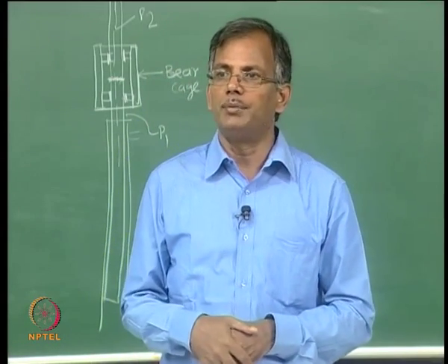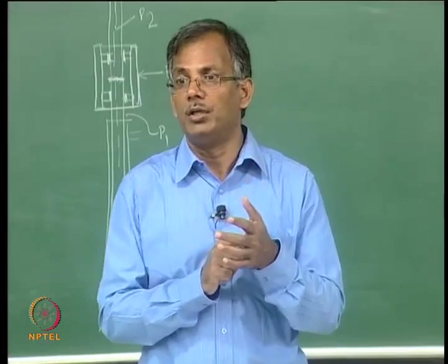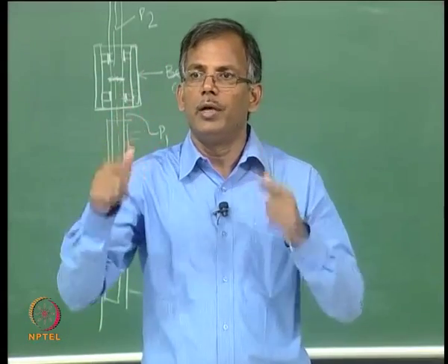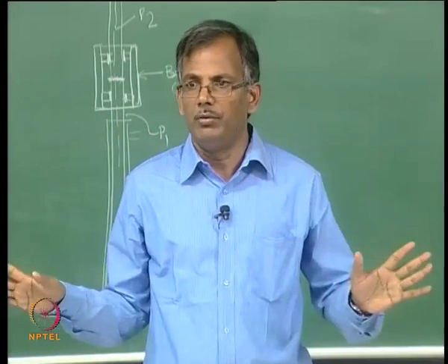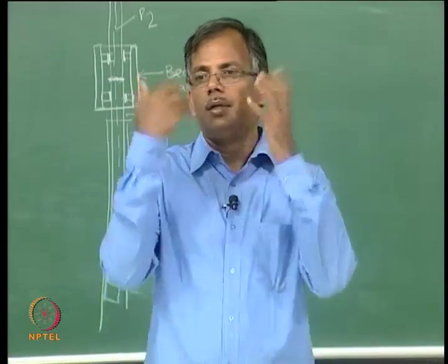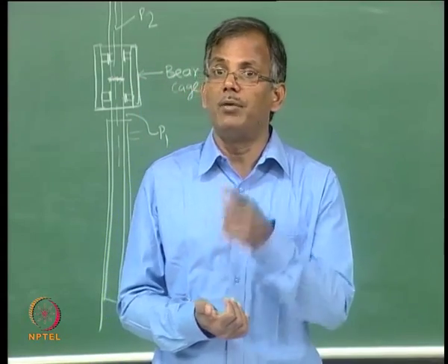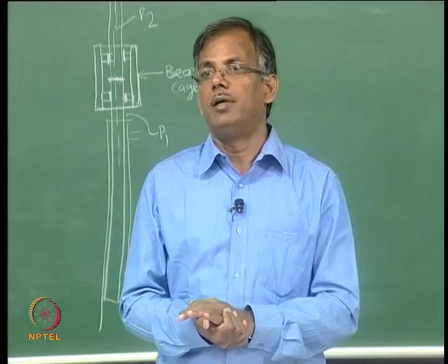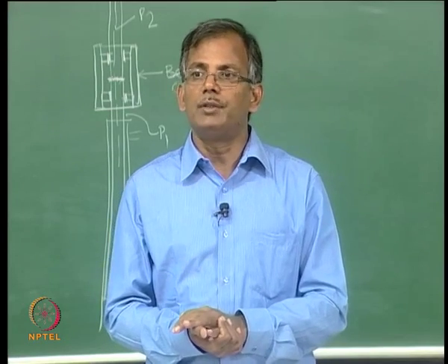If it is unable to absorb, that means at the time of refusal, you will see you strike, no energy is getting transmitted, the pile is not going down, and the energy will be reflected. That is what we want to find out, when it is happening, and basically under what situation it will happen.